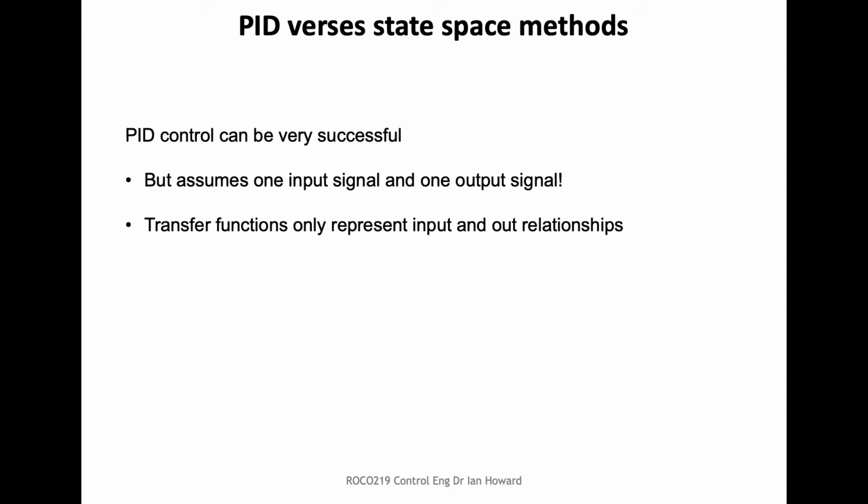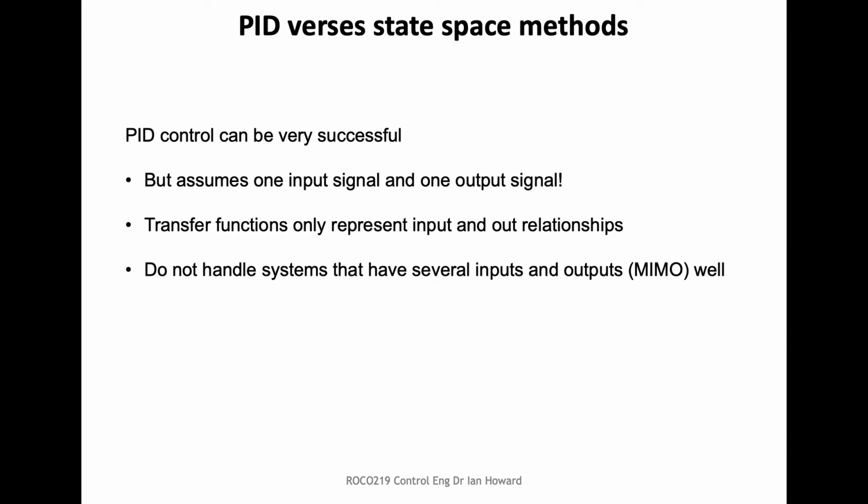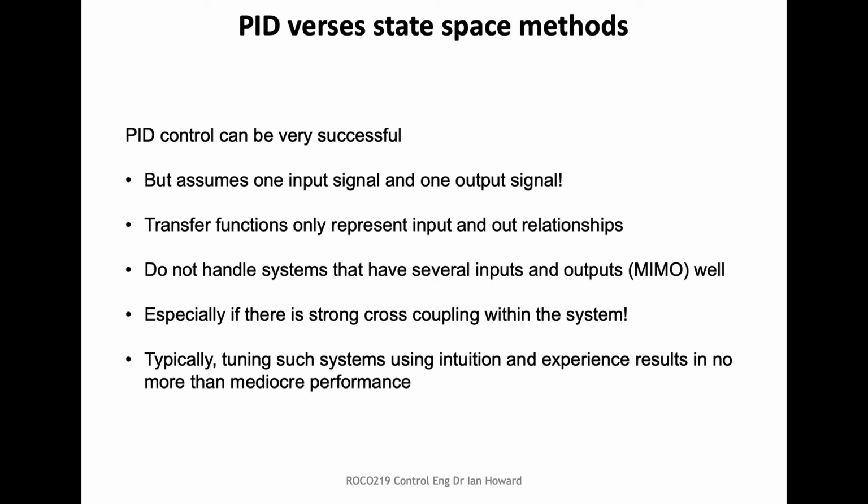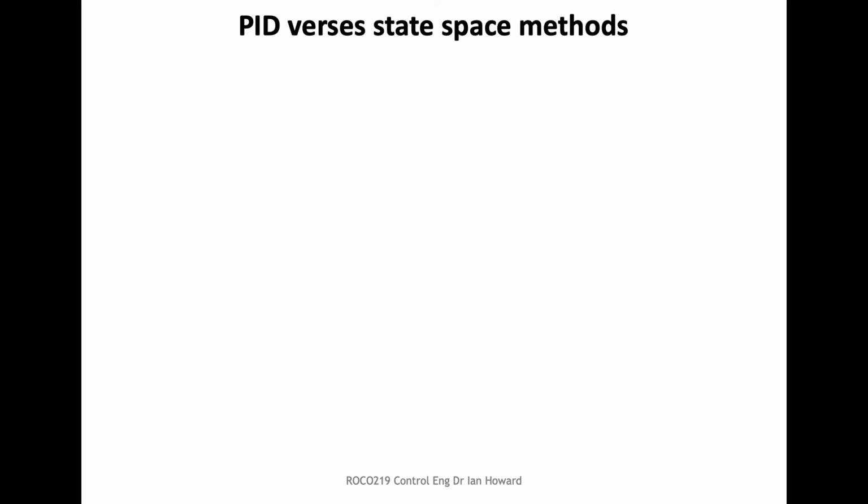they're coupled together. Now the thing that this kind of analysis does when you're using things like Laplace methods and PID control is we're only really interested in, or only representing, input-output relationships using that kind of technique. Now what state space methods will let us do is first of all deal with multiple inputs and multiple outputs that can also be coupled, which is a big deal. And it gives us more principled ways of doing analysis rather than just fiddling with things, which is a bit what we do with PID control.